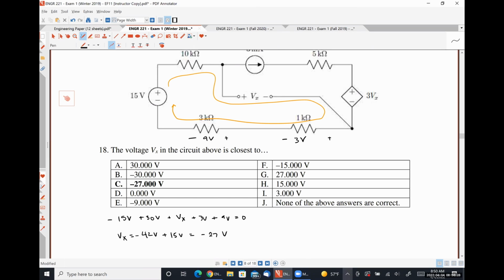So like if you take this Vx right here, it's effectively asking you what you would see if you connected a multimeter between this point in the circuit and this point in the circuit, which does not have to have a conducting path. It's simply the potential difference between those 2 points, okay? So whenever I'm taking my voltage drops over resistors, they have to have a current flowing through them. If it doesn't, the voltage drop is 0. So this is just the voltage drop over an open circuit, right? So it can have any value that it needs to have.